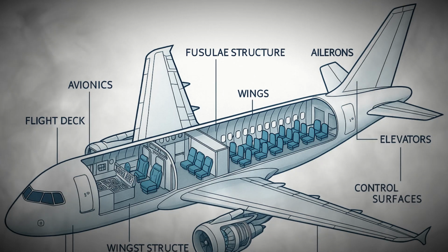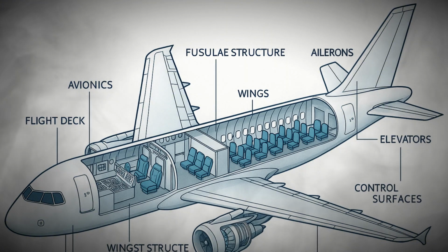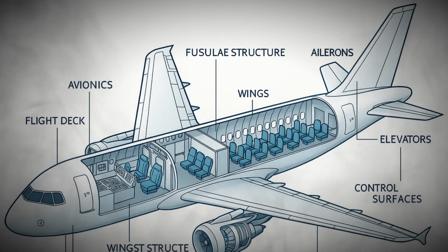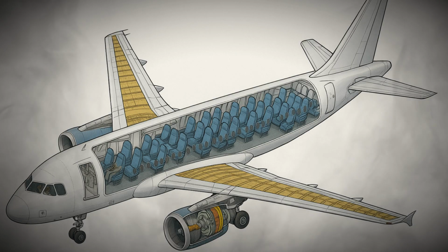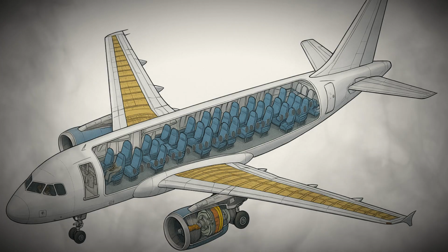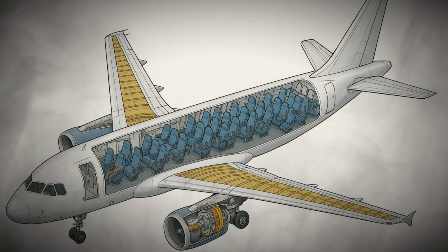Secondary controls, such as flaps, slats, and spoilers, are operated from the cockpit as well. Levers or switches allow the pilot to extend flaps on the wings to increase lift during takeoff or landing. Slats on the leading edge can be deployed to delay stall at high angles of attack. Spoilers are raised to disrupt airflow and reduce lift, aiding in descent and braking after touchdown. Pilots must carefully manage these devices, as improper use can disrupt the delicate balance of forces acting on the airplane.